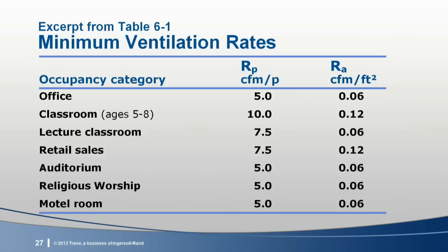Earlier versions of this standard prescribed only 1 ventilation rate for each category. This single rate accounted for the additive nature of odors and irritants, but did so behind the scenes. For example, the 1989 version of the standard required 20 CFM per person for offices. Behind the scenes, that was 15 CFM to dilute people-related odors and an additional 5 CFM to dilute building-related odors.